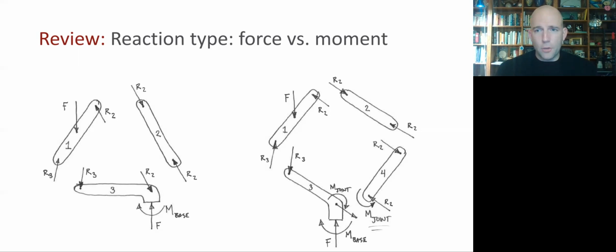Another possibility here would be, say we have a lap joint with one screw or bolt going in there and we tighten it really hard. Now we have this contact patch and we will have friction, and that friction could give us some scrubbing friction to react the moment. But there again, the lever arm of some little patch of friction relative to the center of rotation will be really small. So we're going to need a huge friction force and an even bigger normal force caused by tightening that bolt to get that to work out. So if we can avoid it, we'd like to not have big moments at our connection points.